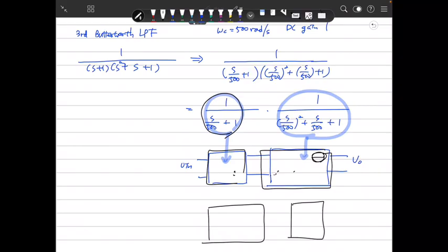But we have not checked about this. So to do this, we have to check that. To make a cascade of the first order and second order filters, you need to check the output impedance. This is 0, or the impedance of the system should be infinity. Then you can do the cascade. But we already know that the Sallen-Key filter's output impedance is 0.